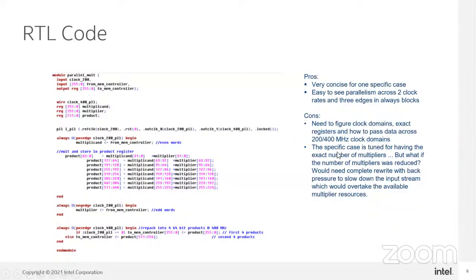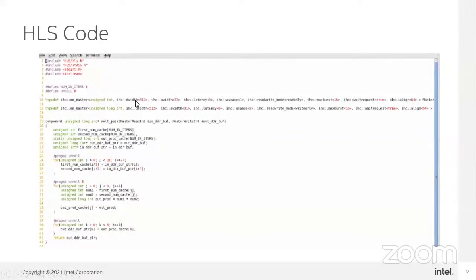The second thing we also need to understand is that it is very easy to see parallelism with respect to the RTL code. And the same code is written in HLS. The greatest advantage here is you can use this as a simple matrix multiplication logic, right?